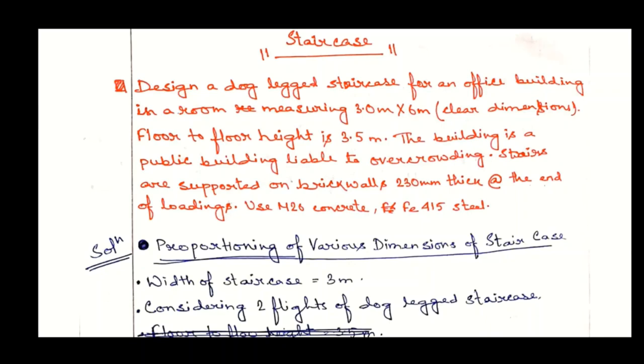Okay, now there are many types of staircase. Among the types, the dogleg staircase is the most economical and common format of staircase. These stairs are arranged with two adjacent flights running parallel with a mid landing. Where space is less, a dogleg staircase is generally provided, resulting in economical utilization of available space. In this type of staircase, the landing is provided corresponding to the level at which the direction of the flight changes.